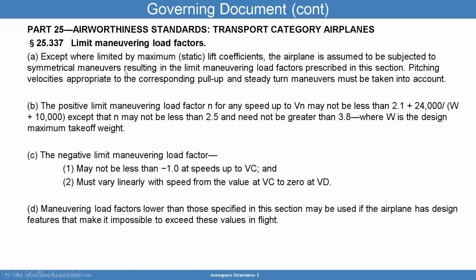We want to also make sure that we are looking at the limit maneuvering load factors. So here it says whenever, except we're limited by static lift coefficients, and we'll be talking about lift coefficients, the airplane is assumed to be subjected to symmetrical maneuvers resulting in limit maneuvering load factors prescribed in this section. Pitch and velocities appropriate to the corresponding pull-up and steady turn maneuvers must be taken into account.